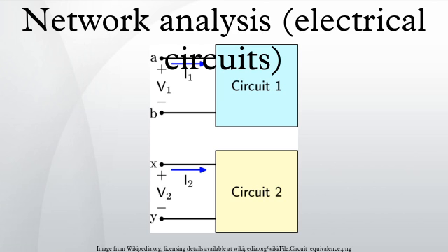For equivalence, the impedances between any pair of terminals must be the same for both networks, resulting in a set of three simultaneous equations. The equations below are expressed as resistances but apply equally to the general case with impedances. Delta to star transformation equations. Star to delta transformation equations.